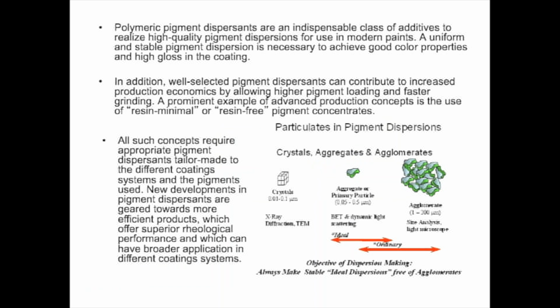So why do pigments need to be dispersed or properly homogenized? It's because of the term phase separation. Okay, solids like to separate from liquids. Oil and water tend to phase separate because of differences in hydrophobicity or polarity. The same with pigments. Pigments are essentially solids that tend to aggregate or phase separate with the medium, the solvent, or the binder. And therefore, dispersing them is important for achieving the right percolation threshold, or minimizing the amount of ingredient but still achieving the same property.